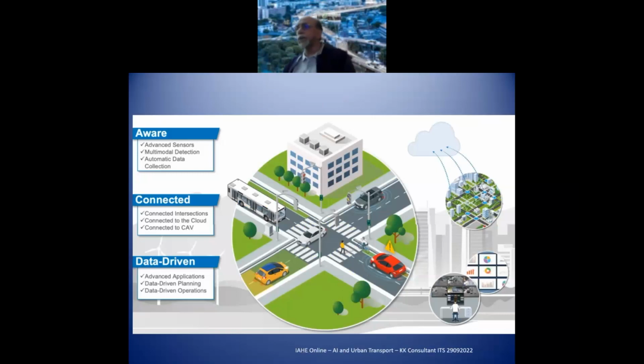Now, conventionally, we used to have a pole in the middle and have 3 lights on 4 sides, which will keep coming. The first generation traffic controllers used simple thermal fuses. Most of the people today won't even know about it. With the thermal fuses, one light glows up and then there is a fuse connected with that. That fuse gets heated up, and after some time it gets fused. And then it goes, and then the next light comes. It has no comparison to what is a vehicle, what is coming, and all that.